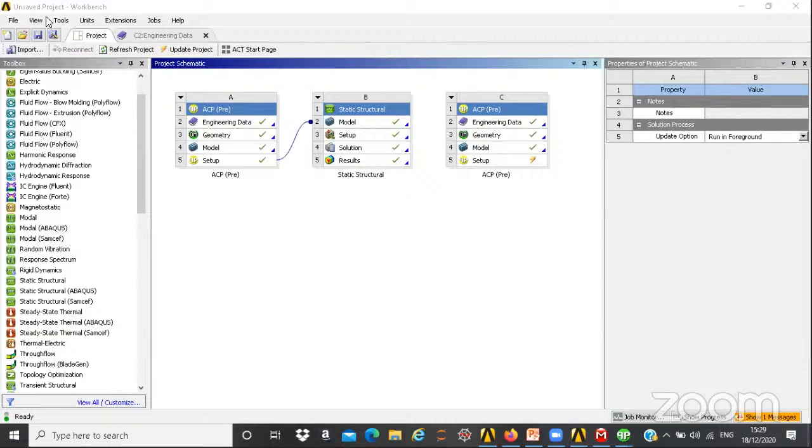Now the same thing can be done in hardware also. So first is simulation. We try it in simulation, then we actually connect it. So the next part will be to actually control, let's say, speed or feed or something basic, and actually monitor the surface roughness through a sensor, or maybe a cutting temperature, or tool wear or something. And then the controller has to change the speed, feed, or depth of cut or any machining parameter in runtime, in real time, so that the surface roughness remains at that 1 micron level. That is towards Industry 4.0. And even this is the beginning. I mean, there is much more scope in this. So we have now come in this direction.